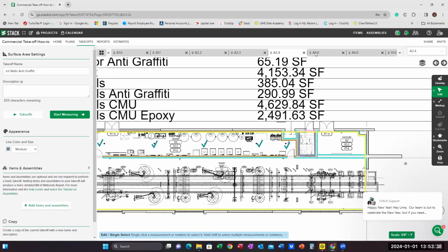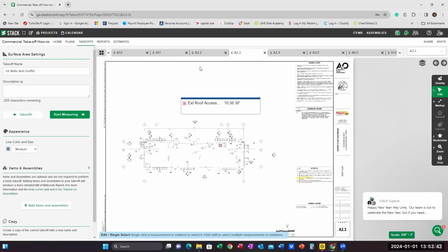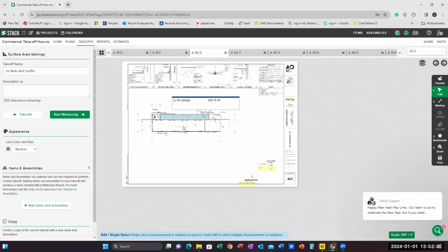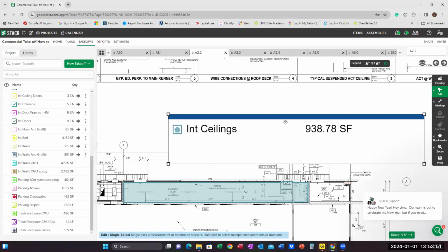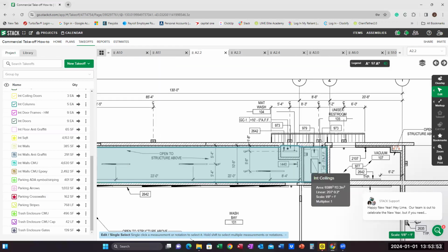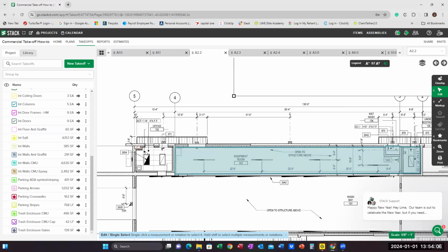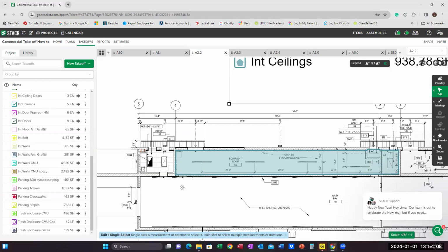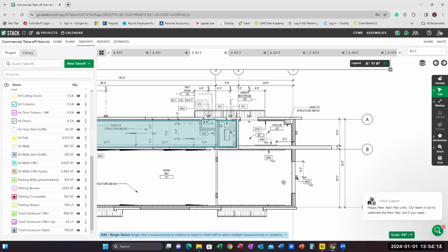And you have to see how high all the walls are. So you go back to your ceiling plan, which is here, and you can find out how tall all the ceilings are. Restroom, 9 foot. This is +9. If it's a +9, I would go with 10 to be safe. It says +9, so I'd go with the next foot up to be safe. That means it's a little over 9 foot, so why not? It doesn't give an exact.